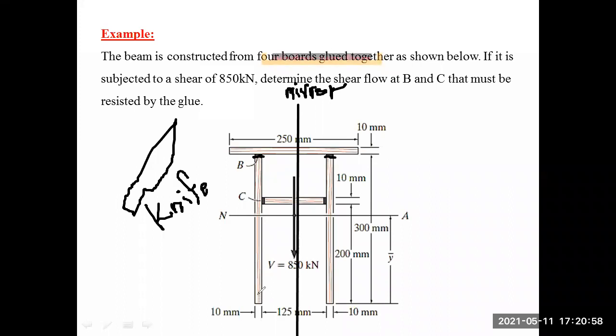No, it's not. I'm not talking about that. This beam is a built-up beam. So these are components, or boards, connected to each other. One board, second, third, fourth, glued to each other at this point, this point, this point, this point. So my question is, if I cut the beam at this point and the mirror does the same at this point, would there be a part of the built-up member that would fall or get disintegrated?